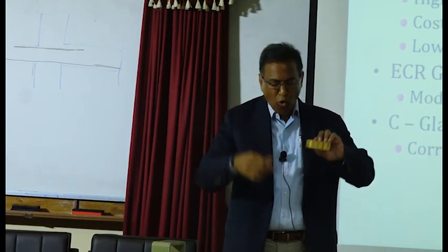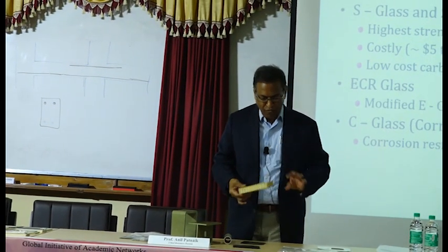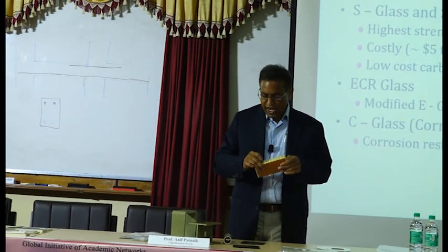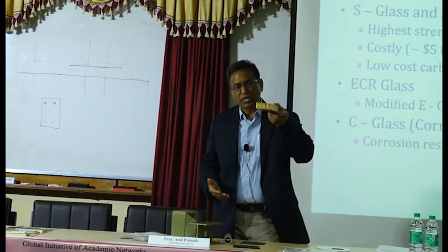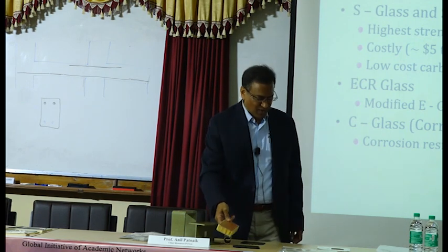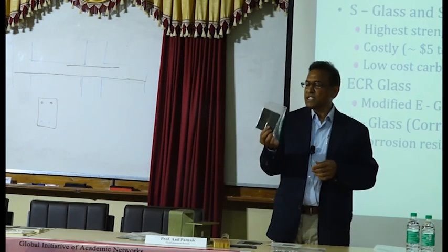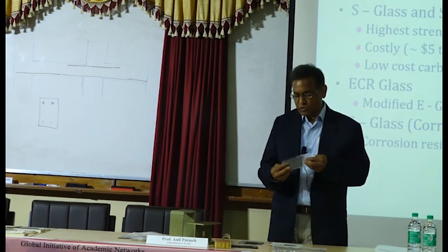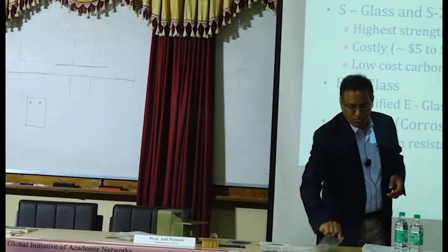You fill the foam, which is structural foam. It's not any ordinary foam. So the foam will carry the shear load and the laminates, the two plates on the two sides of the honeycomb, will carry the flexure loads. Okay, those are the standard ones. This is from a recent application for aerospace industry. We are just starting some research on this, so should be interesting.